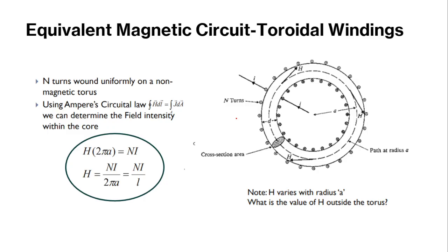Cool. I think you'll know the equation for each, right? When you have a circle or the windings itself, it's the same equation you did before: H is equal to Ni over L. This equation looking familiar? It's the same equation for each, and that's basically Ampere's circuital law.